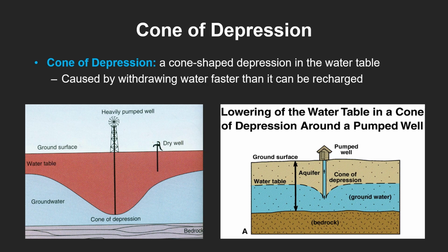When a well pumps water, it creates a cone-shaped dip in the water table around it, known as a cone of depression. If many wells are pumping in the same area, these cones can overlap, lowering the water table even further. This can reduce the yield of nearby wells and impact surrounding ecosystems that depend on shallow groundwater.